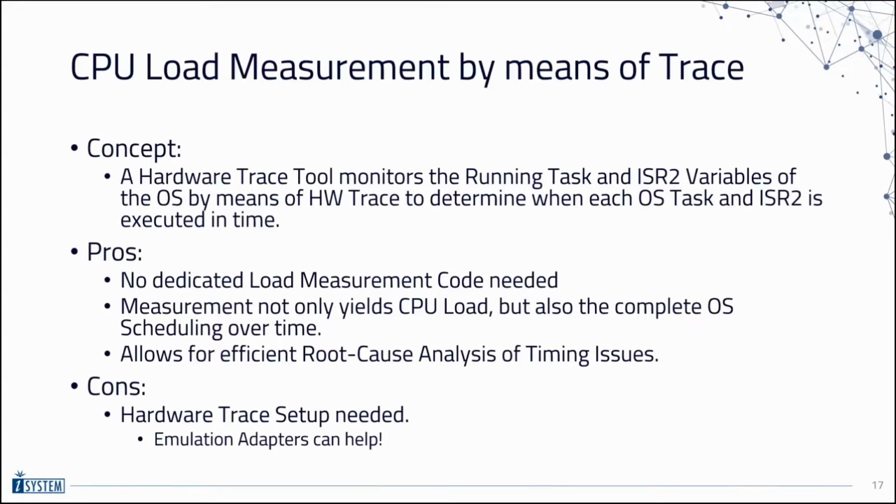For the hardware trace, the chip must support some kind of trace interface. Trace is where the microcontroller has additional logic to non-intrusively record or trace events during runtime. The trace messages can be stored in memory or sent to a trace port where a debug tool like our IC5700 can record the messages.